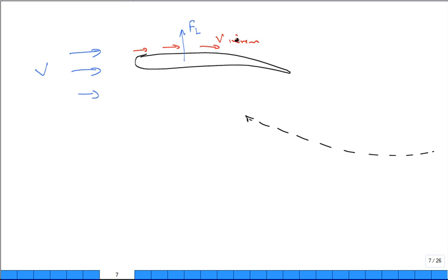Bernoulli, right? Now, we need to stay out of the region so close to the solid that viscous forces are negligible, right? But the pressure can be understood by being a distance off of the solid surface, and that pressure then penetrates into the boundary layer region and is felt, so that the pressure here is like the pressure there. Not saying the pressure isn't changing as I'm moving down the axis of the foil. It's just that in and out of that small boundary layer region where the viscous effects are important, right adjacent to the solid, the pressure is felt directly in there.